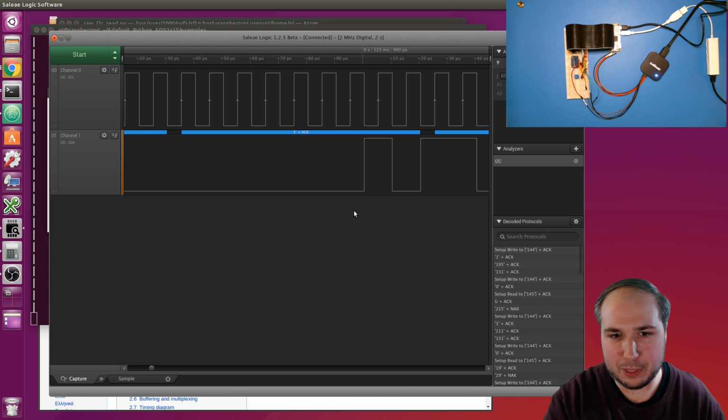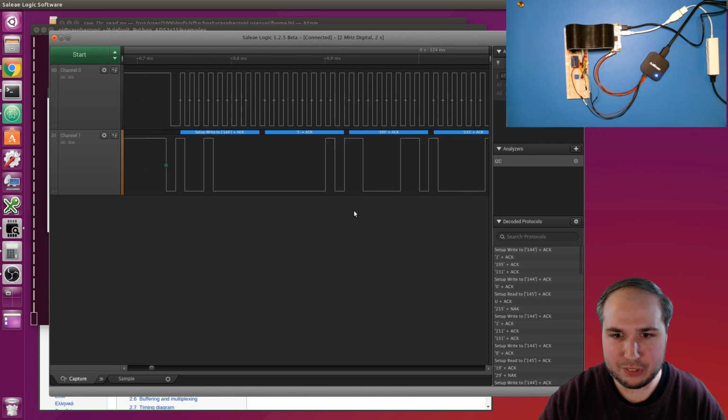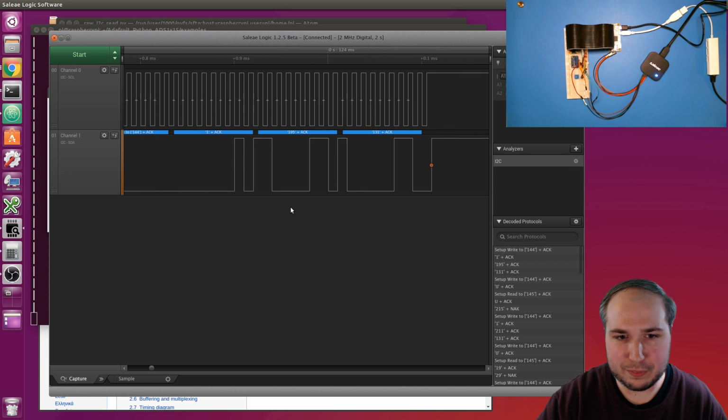You saw previously we told this device we're going to do a write. Now we specified in the next byte the register we want to write to, so this is the config register, and then we're sending 2 bytes of data following this to the config register, because all of the registers on this device are 16 bits, so that's 2 bytes of data that we need to send.